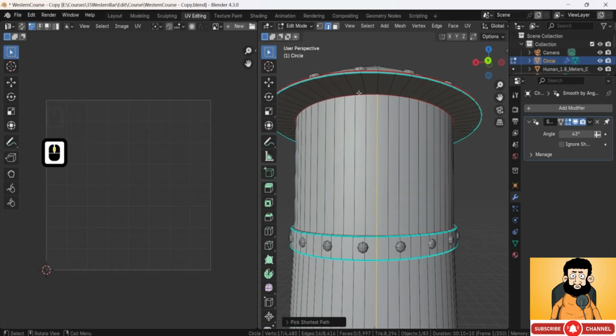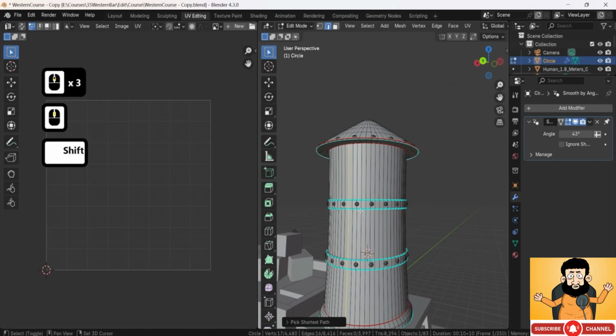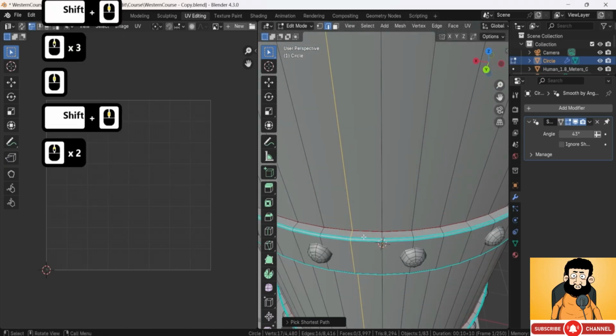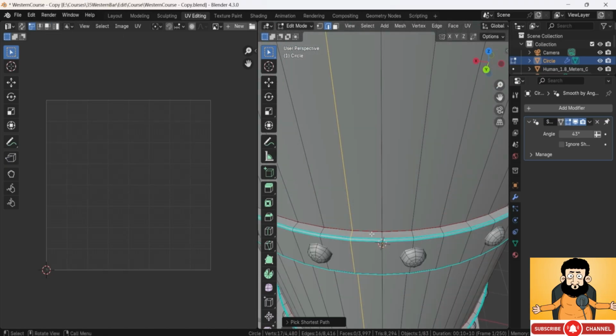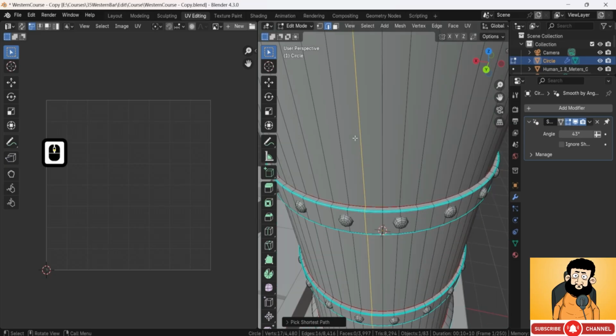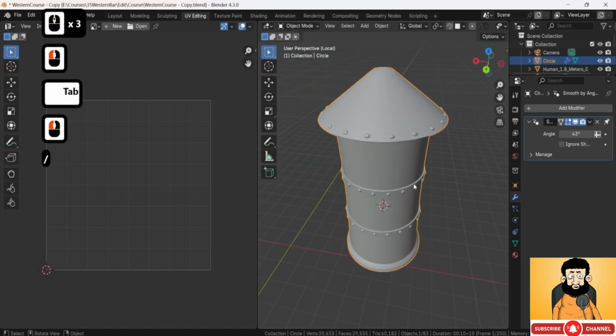The reason being is that they're going to be flattened regardless. They're going to just be circular objects. This, if we think about vertical parts, when they switch to this edge over here, well, let's get back to that in a bit. I want to firstly just right click, mark seam, so we get this out of the way.